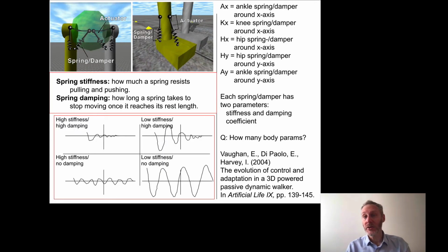However, there's no motors. Remember, this is a purely mechanical device, but they did add springs, and you can see they have one spring that connects the hip to the shank, and then the pelvis to the shank. And then down here in the foot, they have another one on the outside of the foot and the front side of the foot. Let's do the foot first.